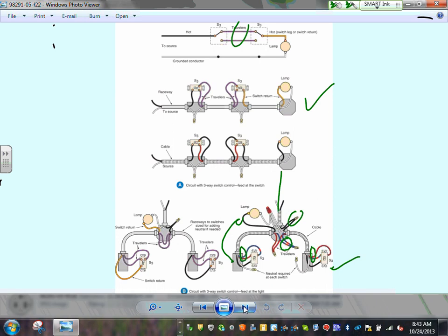If you're using a conductor in 2011, guys, you're required to bring a neutral. As of 2011, you are required to bring a neutral. Guess what's happening, Adam, in 2014? There's an exception for this, where if you have a 3-way switch, you can bring a neutral only on one side. One more time. If you're wiring with cables, you have to bring a neutral to every switch. If you're wiring with conduits, you don't, because you can pull a neutral at all times.